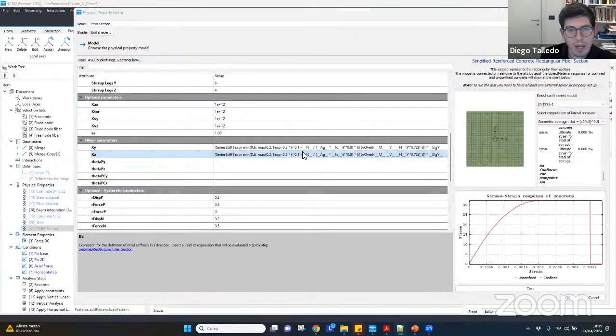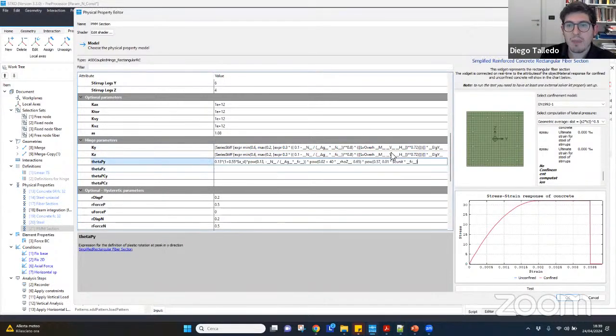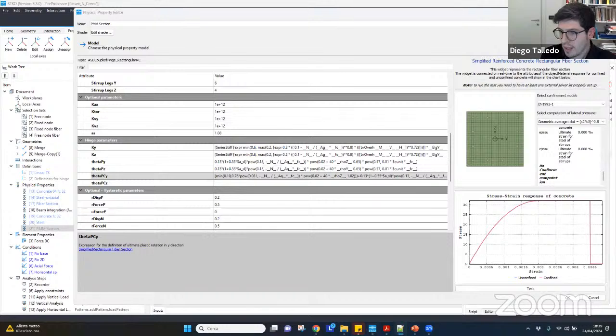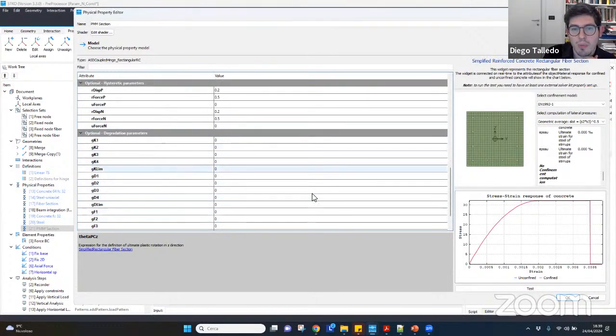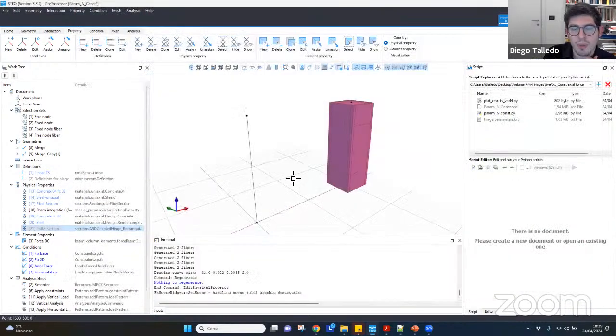We have the relations as placeholders. We have my, mz, vy, vz, etc. If you just write v and m, it automatically understands what the needed values are, independent of the direction it's considering. So this is done automatically by STKO, and by OpenSees, of course. And I don't want to touch the hysteretic parameters, which are all optional, because we will first perform a monotonic load test. So basically, we created our simplified section.